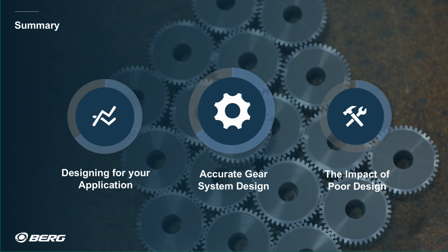Today we have addressed the issue of premature gear failure resulting in unplanned downtime. We have established that gear design choices early in the development process, along with preventative maintenance care, can extend the operating life of any gear drive system. We have stressed that application constraints are the single most important factor in determining the correct design, and that you must consider torque, shaft orientation, the transfer of power, and the environment to produce a gear drive with a long lifespan. We have called out AGMA Gear Quality Standards to help you determine the correct quality specs for an intended application, along with shaft and bearing design.